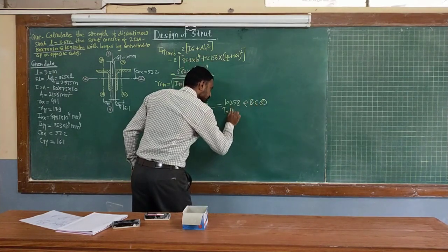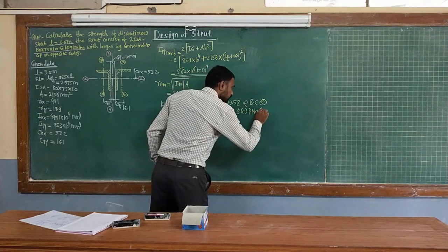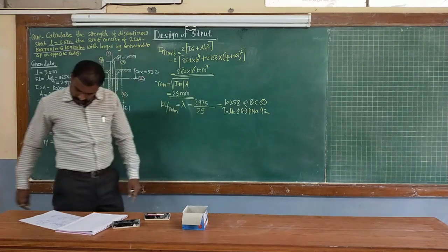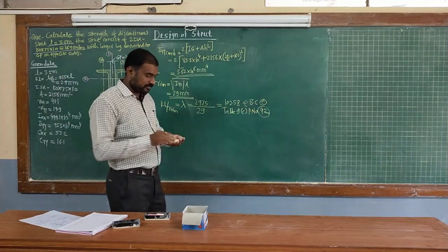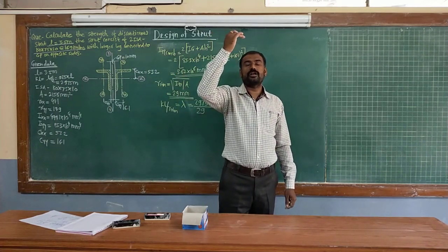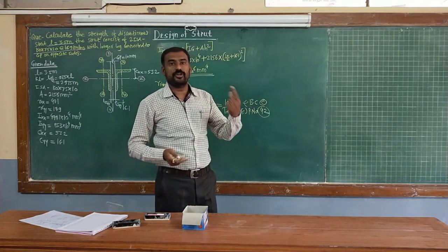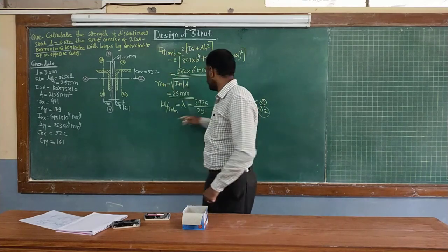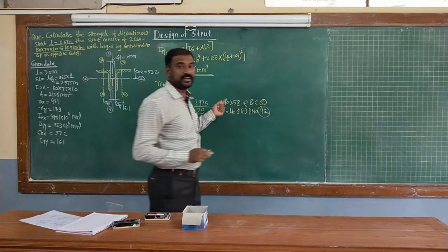Table 9C, page number 42, correct? Yes, this is page number 42. On that you can observe that the values of slenderness ratio are lesser towards the top side and increasing towards the bottom side, but the opposite is the case for FCD value, correct? Our value 102.58 is ranging between 100 and 110.